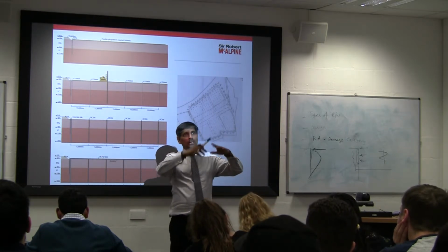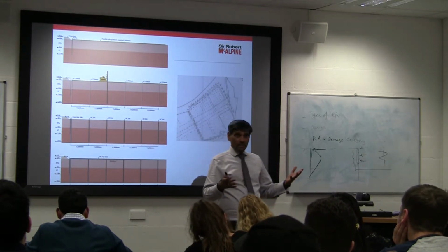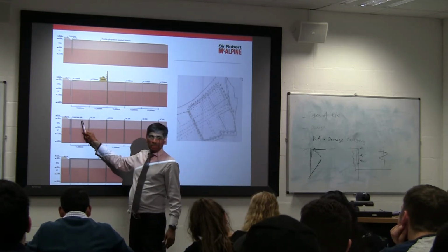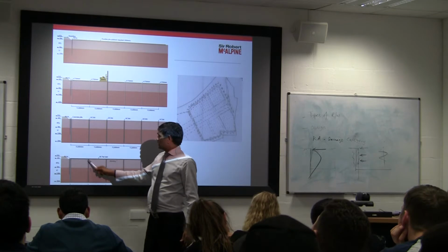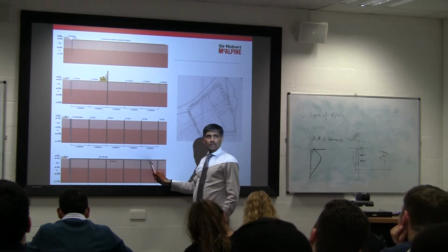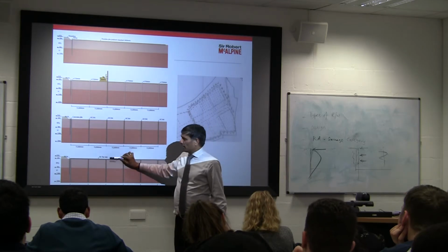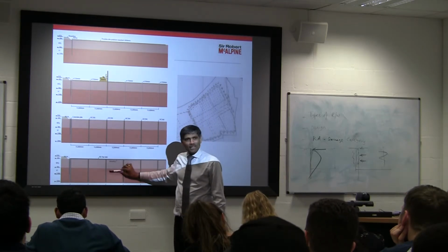Normally, if you are pouring a concrete slab, you need to put a shutter, right? So you've got to put the shutter. Here, we are using the ground as a support for the shutter. So we cast the concrete slab here. So, it means you can start working on the slab before you start digging.